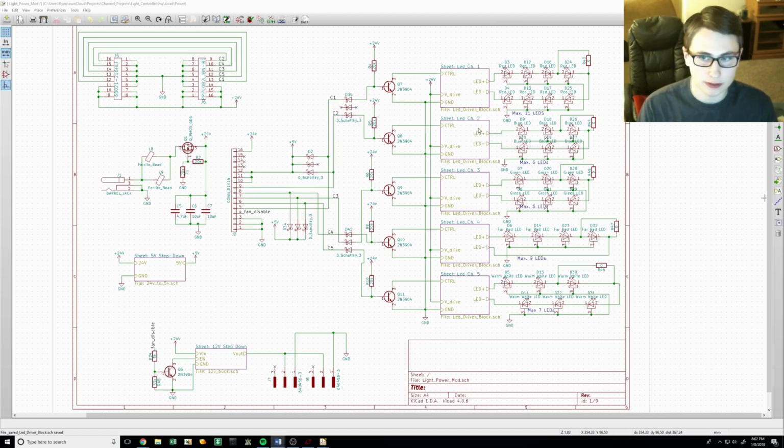For this project, I designed one switch mode power supply current regulator for the LEDs, and then duplicated that schematic element 4 times, one for each color. This is a step-down switch mode power supply, and it does not use a traditional topology, placing the load in series with the inductor.